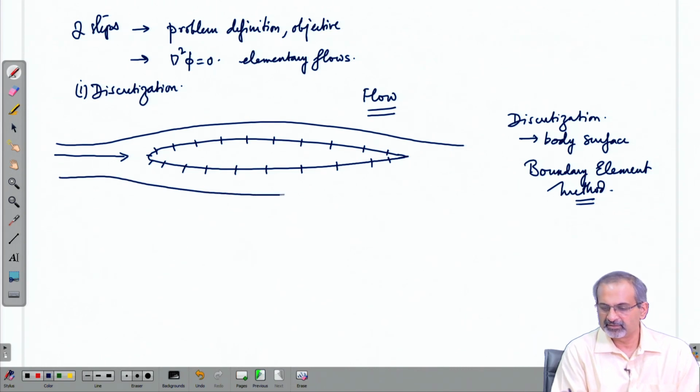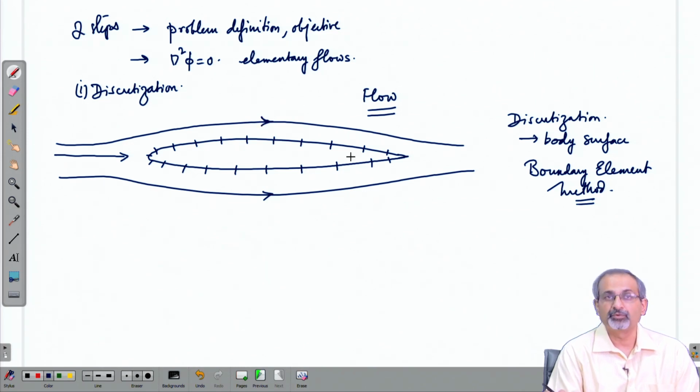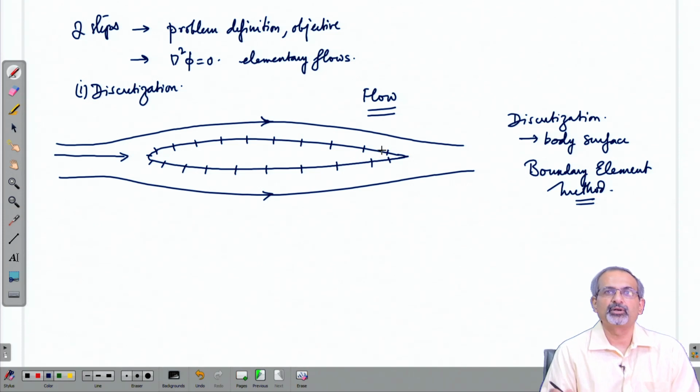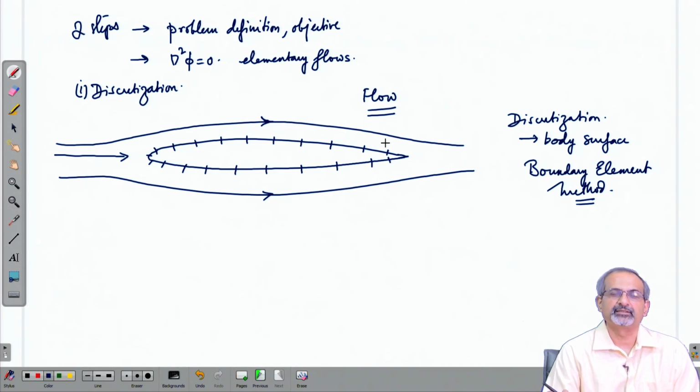That means, streamlines like this will never come out of a solution like what we are trying to attempt, but we will find out still what is the pressure which is acting on the surface of the body, what is the tangential velocity component on the surface of the body and so on. Here we are solving potential flow, therefore, the flow will slip on the body surface, there will be tangential velocity component, but there will not be a normal velocity component.